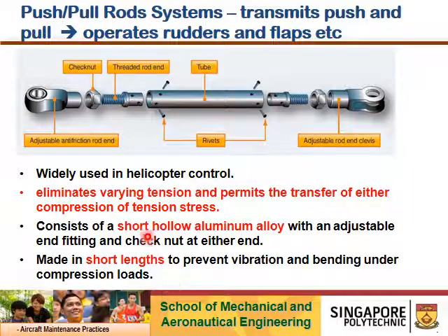It consists of a short hollow aluminum alloy tube with adjustable end fittings. The only limitation or shortfall of the push-pull rod is you can only have a short length of travel to prevent vibration and bending due to compressive load.